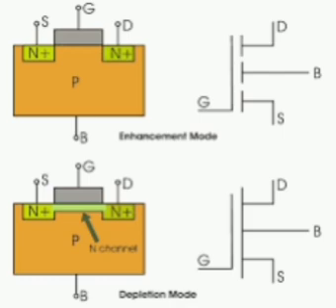The value of gamma E and B is very close to 1, and in ideal conditions it is 1. In a diffusion transistor, base current is only due to diffusion. In a drift transistor, base current is due to diffusion and drift phenomenon. The recombination agent used to trap charge carriers is gold.